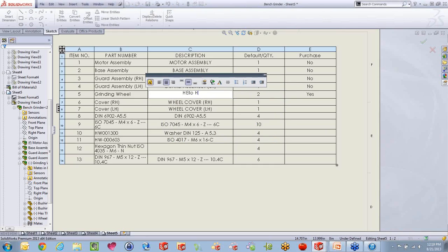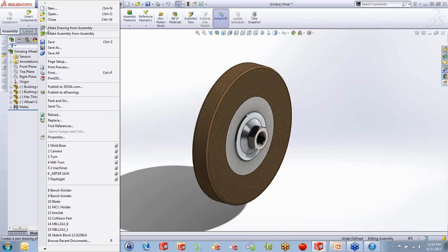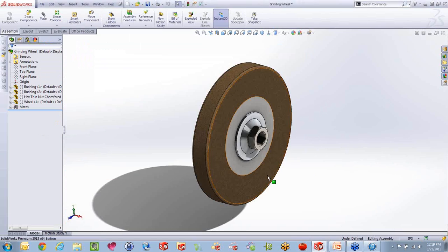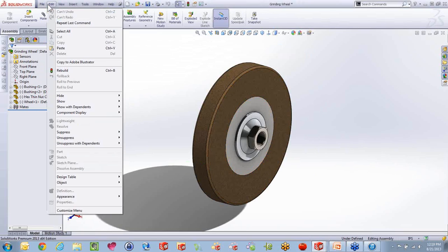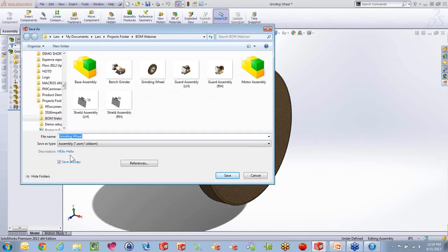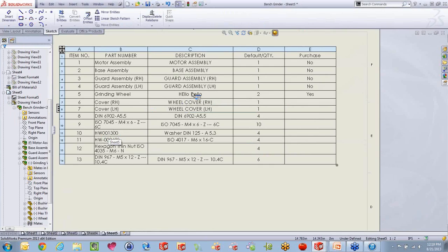And if I type something in here, then it actually goes all the way back into our property on our file. So it actually goes both ways. So now you will see that that got put in there. And of course, SolidWorks is that cool that if I go and say Save As again, it has actually also been populated into my description. If you didn't know that, that's maybe a pretty cool way to deal with that kind of stuff, that we can actually populate things back.